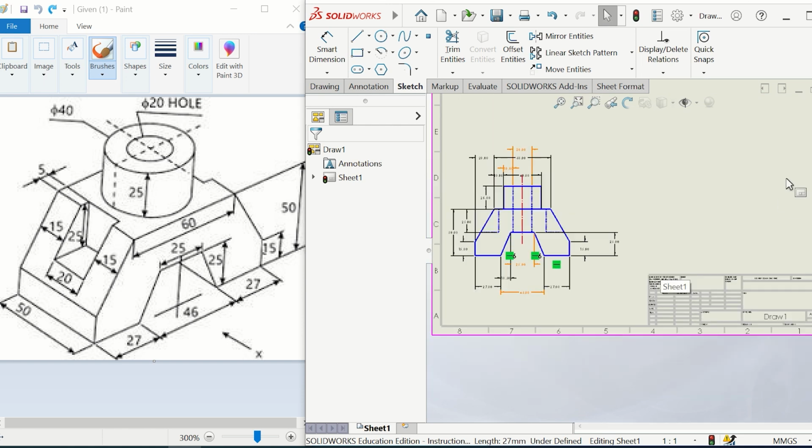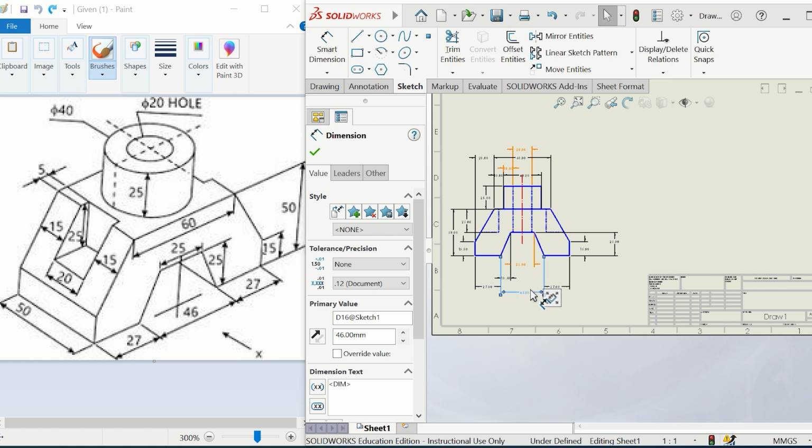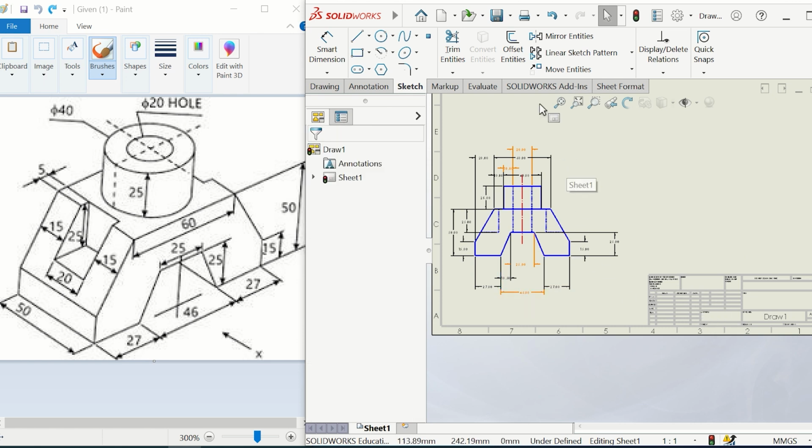This is above it, which is fine. However, if I draw the right side here, and I want to place dimensions under it like I did here, I might have to come to the area which is overlapping with the title. If I place a dimension like this one, similar to this dimension here, and it extends all the way down to this table, then I can simply move all of these entities.